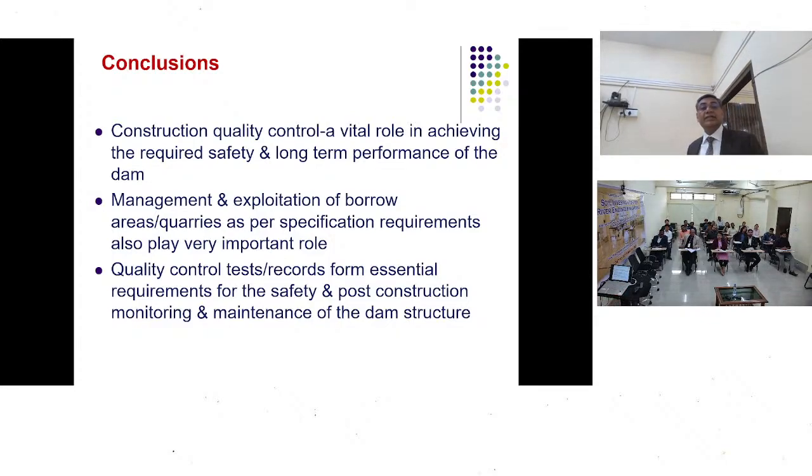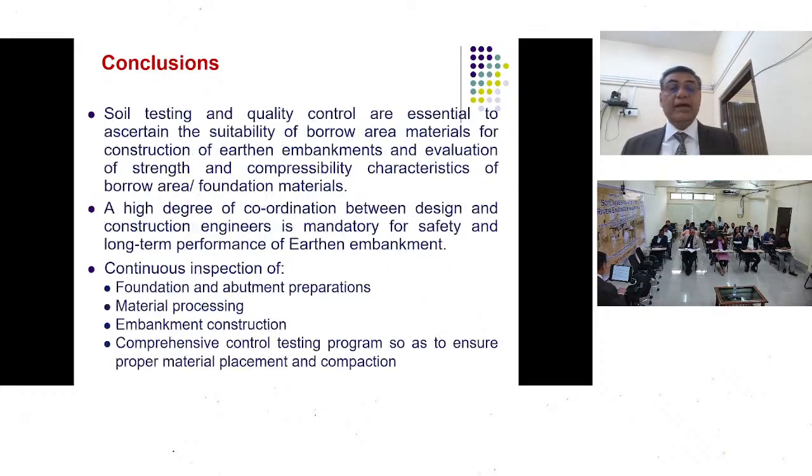So, conclusions, we can say construction quality control plays a vital role. Management and exploration of borrow area, quarries as per specification requirements also play a vital role. Quality control test records form essential requirements for safety and post-construction monitoring and maintenance of dam structures. Soil testing and quality control are essential to ascertain the suitability of borrow area materials for construction of earthen embankments and evaluation of strength and compressibility characteristics of borrow area and foundation material.